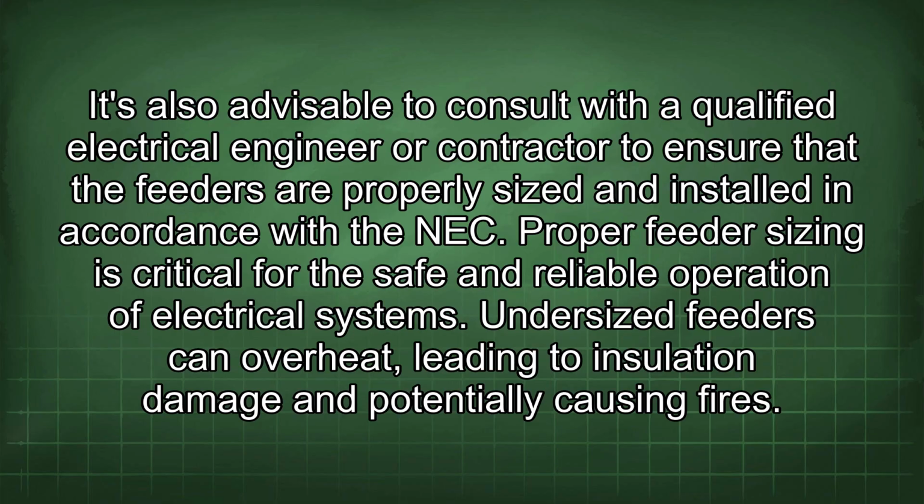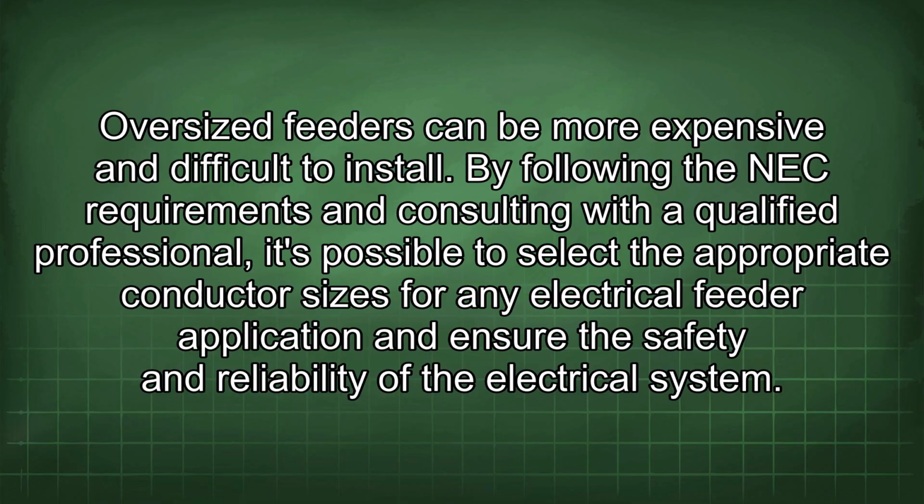Proper feeder sizing is critical for the safe and reliable operation of electrical systems. Undersized feeders can overheat, leading to insulation damage and potentially causing fires. Oversized feeders can be more expensive and difficult to install. By following the NEC requirements and consulting with a qualified professional, it's possible to select the appropriate conductor sizes for any electrical feeder application and ensure the safety and reliability of the electrical system.